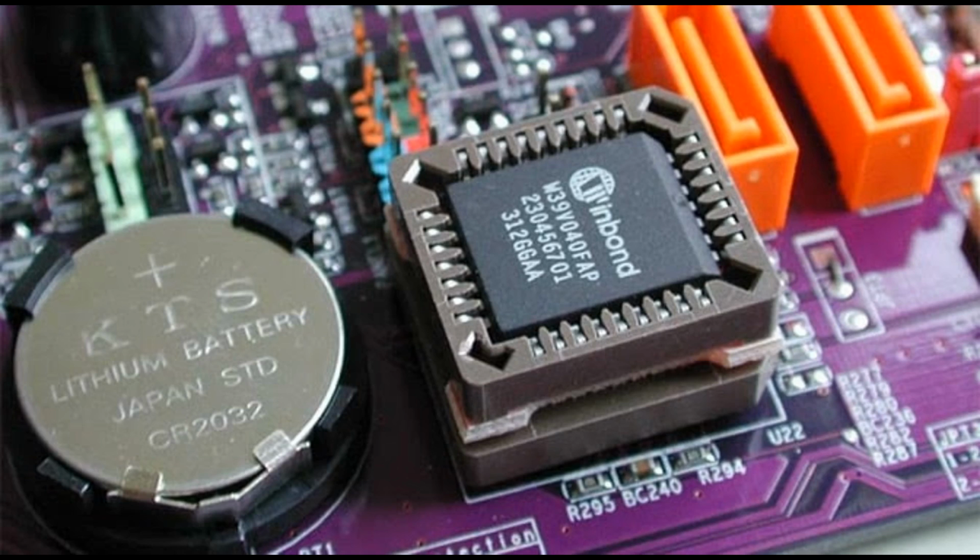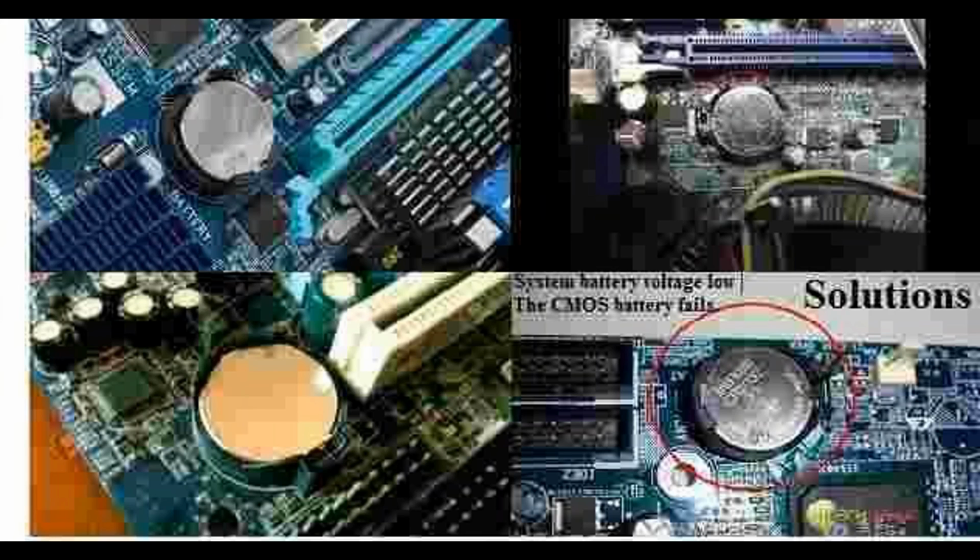Analog and mixed signal circuits. CMOS technology is also employed in the design and fabrication of analog and mixed signal circuits, including analog-to-digital converters, ADCs, digital-to-analog converters, DACs, amplifiers, filters, and sensor interfaces. CMOS technology offers advantages such as low noise, high linearity, and compatibility with digital circuits, making it suitable for mixed signal integration.